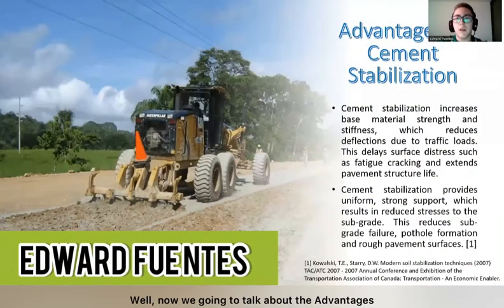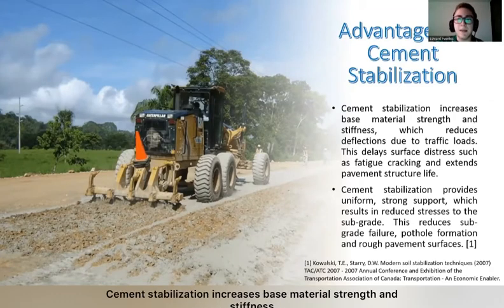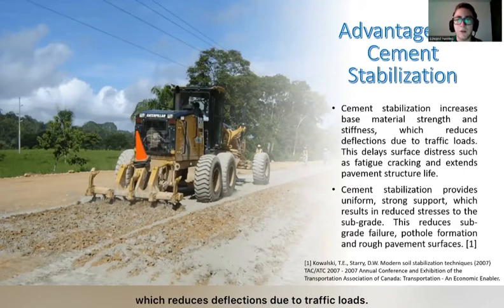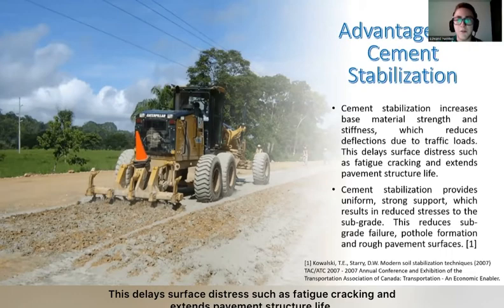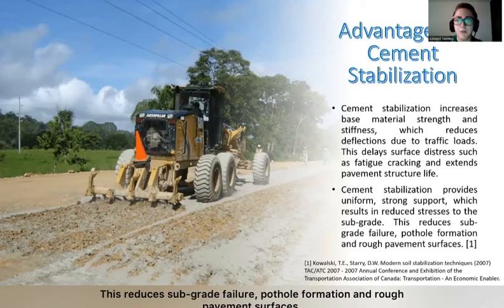Well, now we are going to talk about the advantages and disadvantages of cement stabilization. In the advantages, cement stabilization increases base material strength and stiffness, which reduces deflection due to traffic loads. This delays surface distress such as fatigue cracking and extends pavement structure life. Cement stabilization provides uniform strong support, which results in reduced stresses to the subgrade. This reduces subgrade failure, rut formation, and rough pavement surface.